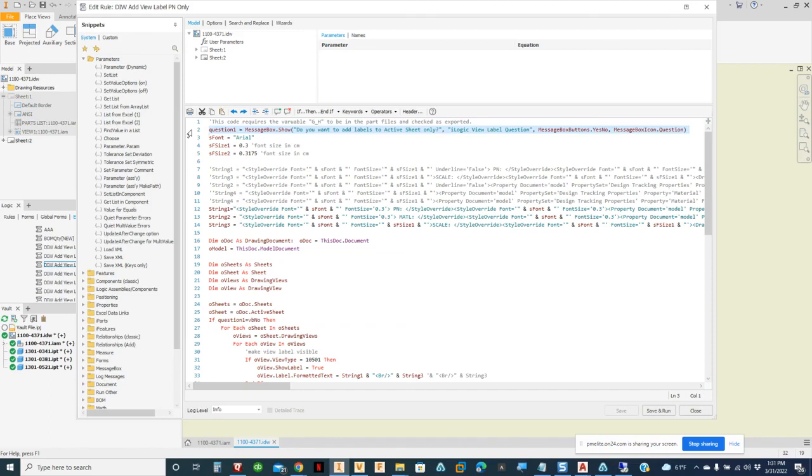And that's nice to put those kind of things in the iLogic, is just try to think about, if you're using the code, how do you want it to work? The other thing that I like to do is to provide functionality and flexibility. So if Juliana is working with me and she's doing her drawing, she might want a certain type of font and a certain text type. I might want something different. Having the ability to change that is nice. So you can actually set the font that you're looking for. I have two different sizes. If the scale might be smaller than the actual text or the part number, you can control it. This, I'll just get rid of.